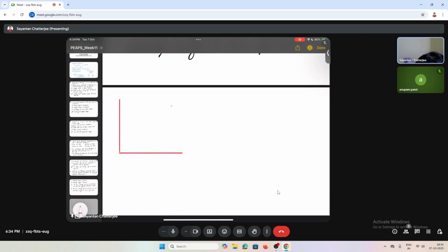So this is for Statcom, and let's say this is the initial operating angle. With the disturbance, this may go up to this point, and at a certain point of time, if these two areas match, the system will be in a stable condition.